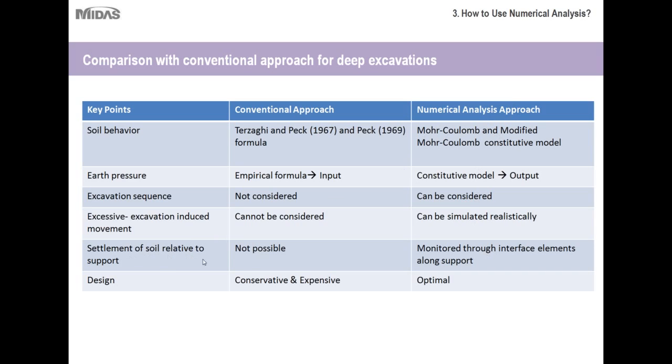Settlement of soil at relative support is not possible with conventional approaches, whereas with the numerical analysis approach, it can be monitored through interface elements along the support. That's another thing I'll show you very briefly during the demonstration, just the interface elements. And the design for a conventional approach for larger scale projects anyway is very conservative and expensive. For smaller scale projects, it's still conservative, but it's still economic just because of the project conditions. Whereas with larger scale projects, numerical analysis is very optimal and very cost effective.